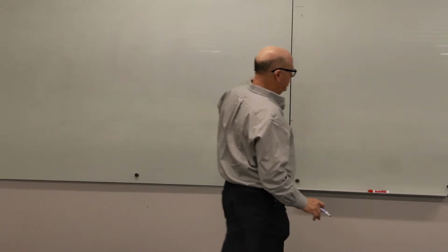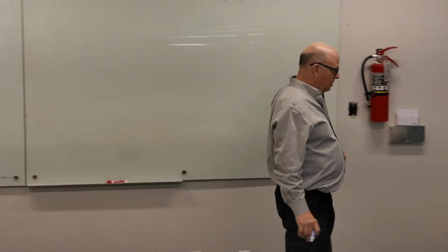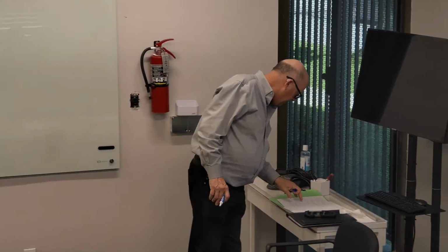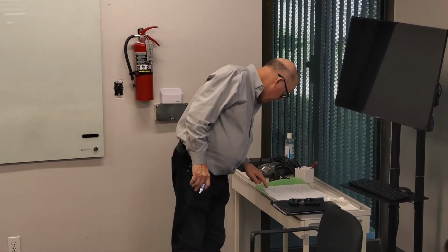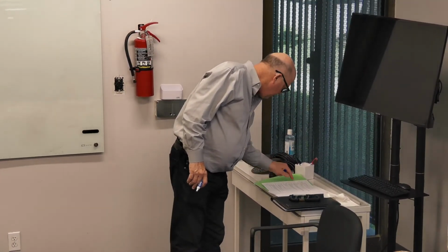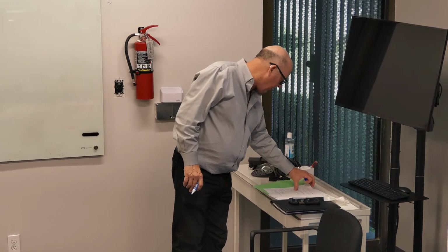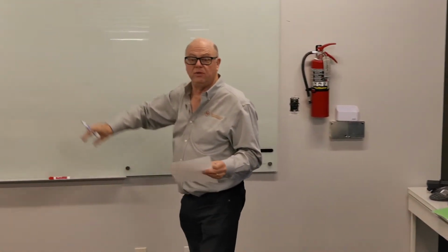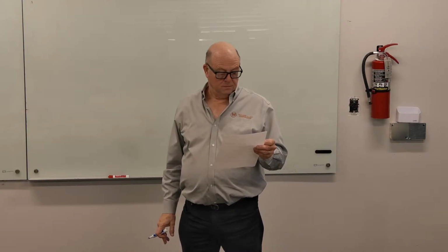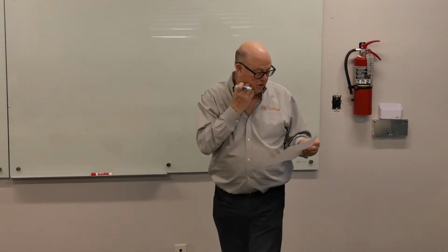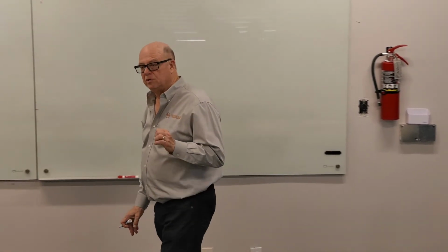Okay, so we went backwards. We've used half of our time. Now I can go to item 2. We talked about left and right hand. We've talked about discharge configuration. We talked about how you fit it in the equipment room. You know what we haven't talked about with air handling units is blow through and dual duct, whether it's dual duct with mixing boxes or dual duct VAV.